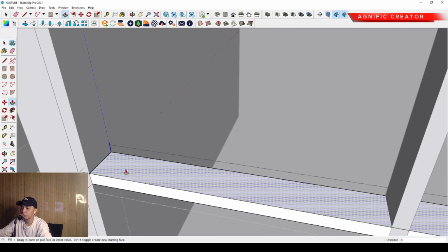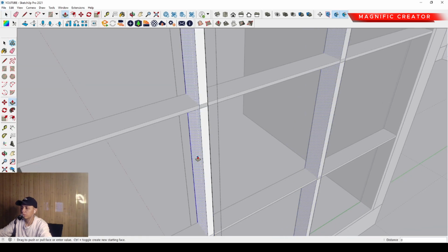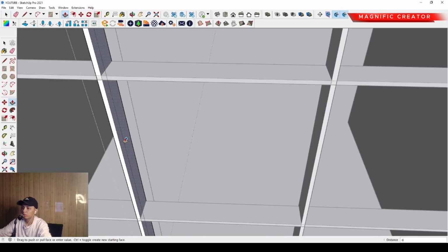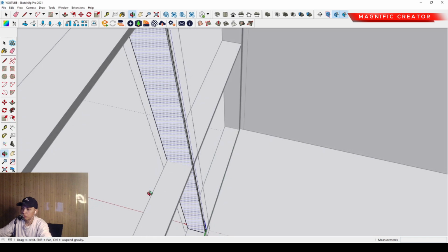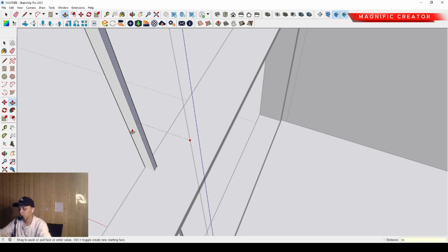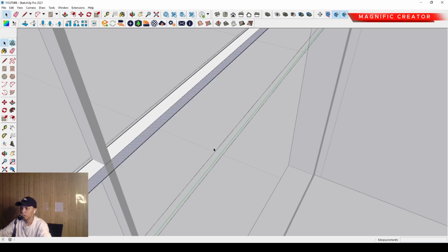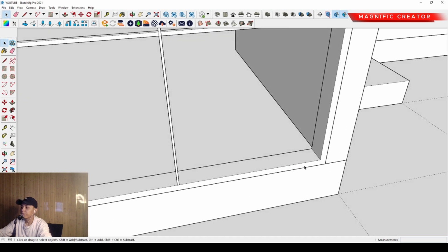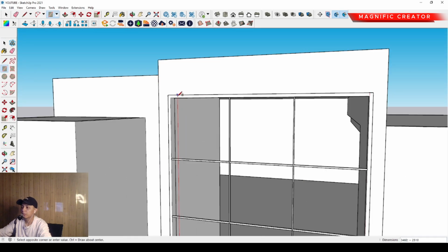Then we can select move and press Ctrl to duplicate it, and then we can place on this position by typing 4/ and it will automatically divide for this horizontal frame. So when we make it more slim in thickness, we have to make it slim also, around 15 and 15 here. Okay, so then we can make another slim one to the front around 100. And this one also 100, just like this, so we can separate it.